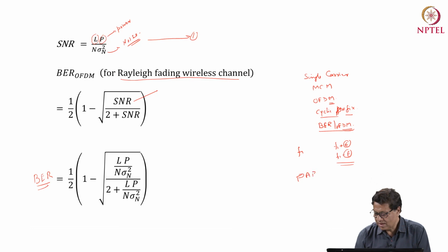and also we will discuss the problem of PAPR, that is peak to average power ratio, which is quite common in OFDM. This PAPR is generally high for OFDM signals, and this is not a suitable thing for our optical wireless communication systems, because high PAPR will make the LED system go into a nonlinear mode, because it has only a limited dynamic range, and then it is almost constant.